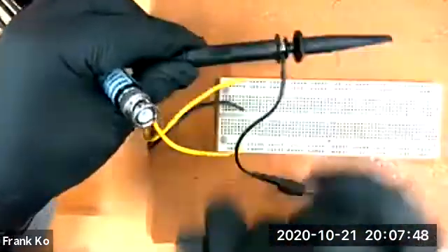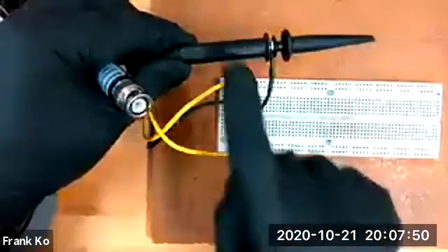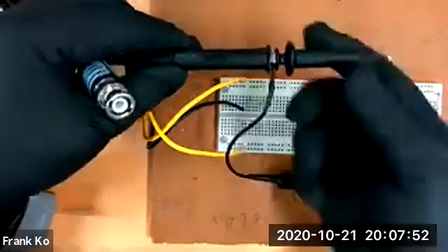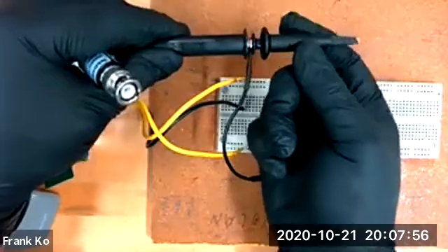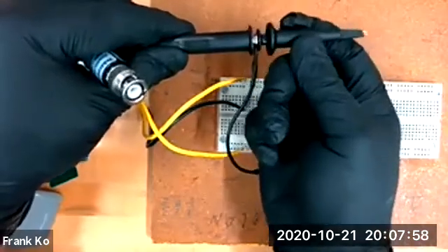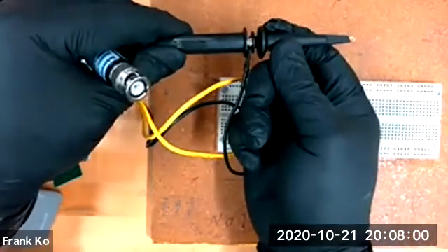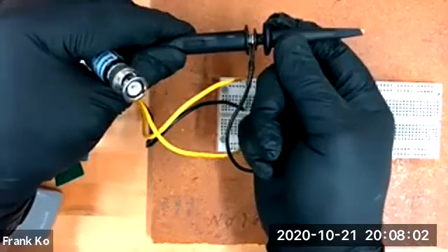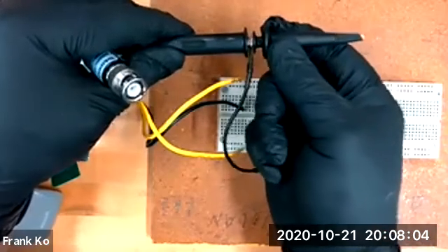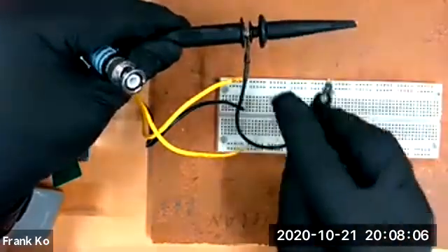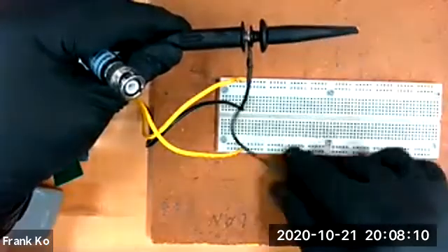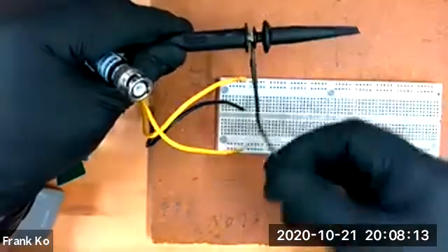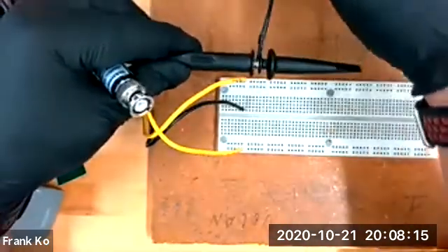There's a slider between 1x and 10x, so slide it to 1x. Notice here also, if you push on the body of the probe, it will reveal a hook coming out, and that hook is what you're going to use for making a connection. And then you also have an alligator for ground lead. Notice this also, the ground lead can spin around